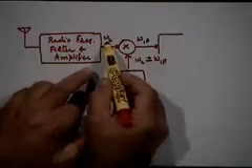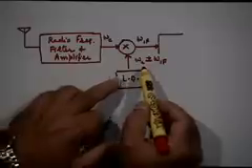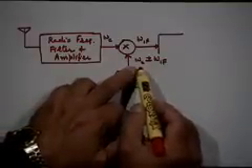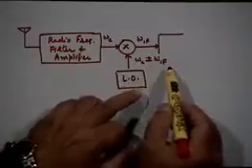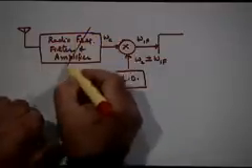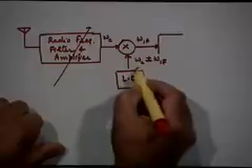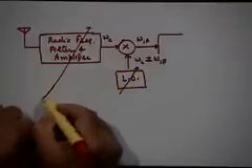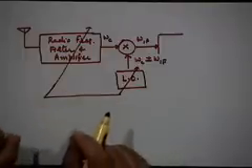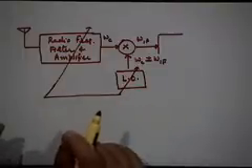If this goes from omega 1 to omega 2, this should change from omega 1 plus omega IF to omega 2 plus omega IF. As this is tuned, this also should tune. So this tuning is typically ganged up, right. This happens together through a single ganged up set of capacitors or whatever.